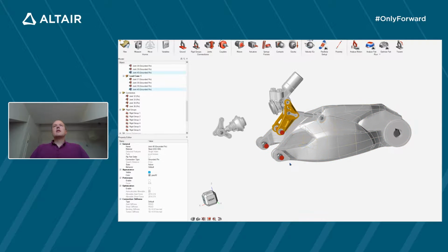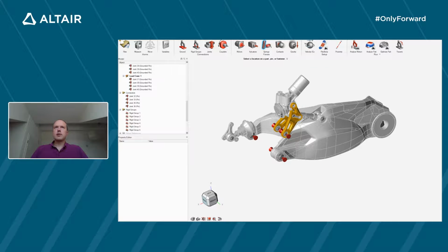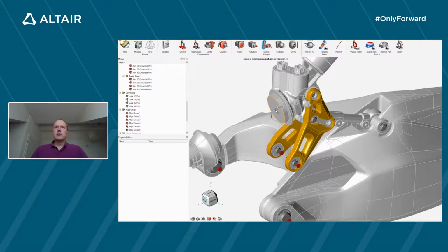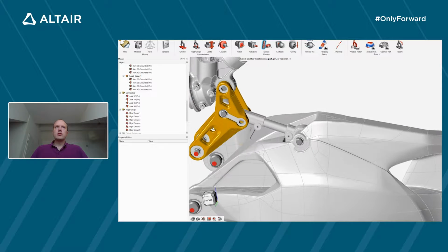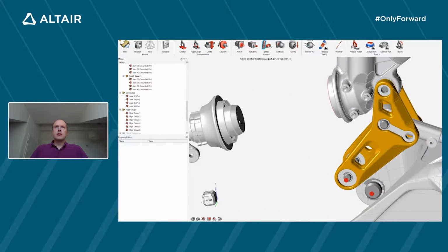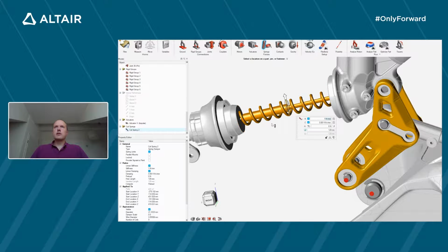All right. Now, the setup would still need some more definitions, like, for example, defining actuator and spring systems if they are in the assembly. And the spring, for example, can be defined by, again, clicking on your geometry parts. For example, going to the center point of this surface here as the first starting point of your spring, then rotating your view a bit and going to the center point of the opposite surface to define a spring here.